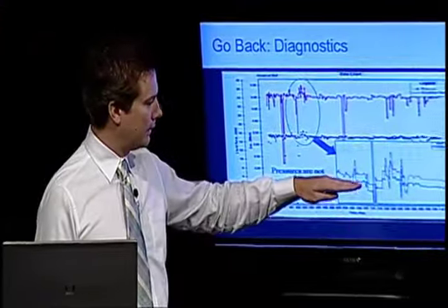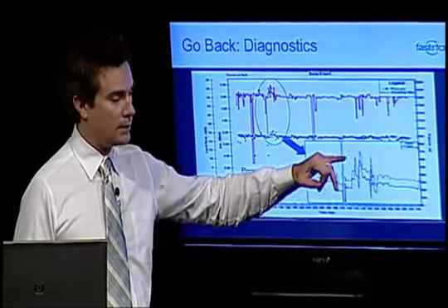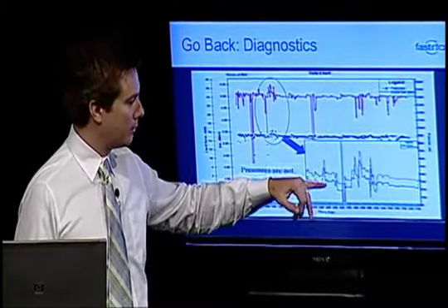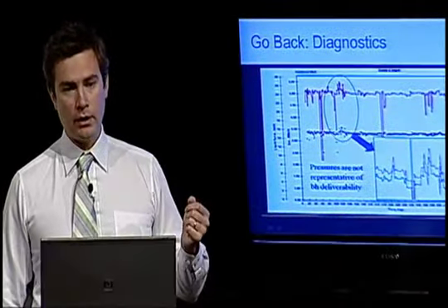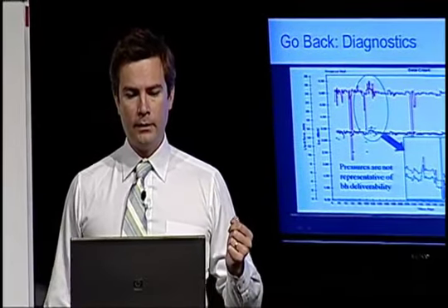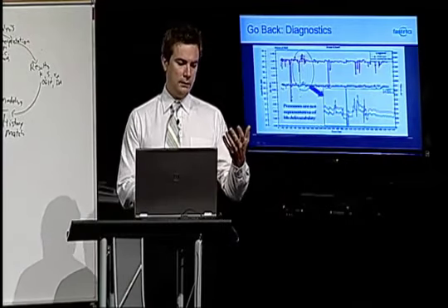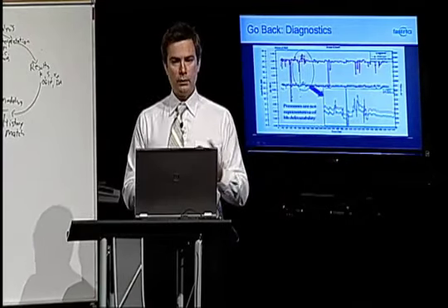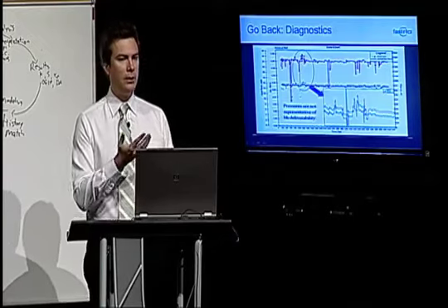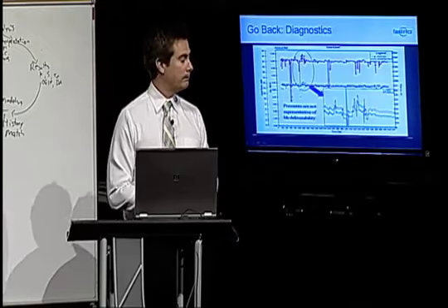You're really just getting a sense of the gas rate that's in the system. As the gas rate goes up, the pressure will go up in the system. They're correlated with each other exactly. So that's not very valuable to me. That's not telling me anything about the sand face inflow, which is really what I'm looking for with pressures. I want to know how the operating conditions are changing.